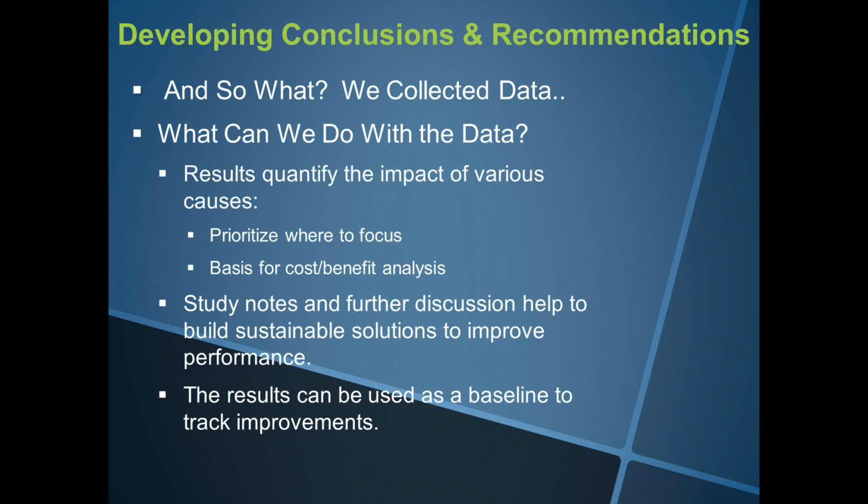So again, I think the big criteria is how much variation there is in the process and how long those cycles are. And that would be the same criteria I would give for doing a time study as well. Statistically, the shorter the cycles, the fewer observations you need, and the more variation, the more observations you need. Does that answer your question? Yeah, makes sense.